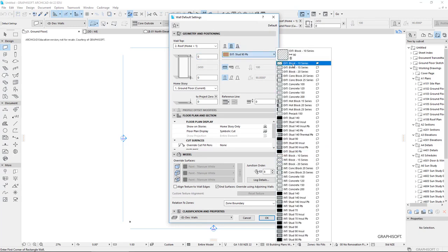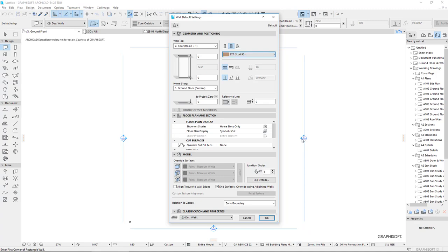If you want to make it out of blocks, then certainly choose block. I'm going to choose just an exterior timber, which we call studs, not lumber, but it's an exterior stud wall. Just a plain, simple wall. Now this option here is where we just have a basic structure. This one has the composite, so we have lining on the inside, we might have cladding on the outside. For this project, let's just use something really simple, just a very simple wall. It's not going to taper, it's not going to be trapezoid, and we're going to create a not linked wall.